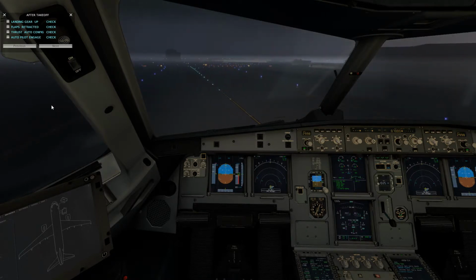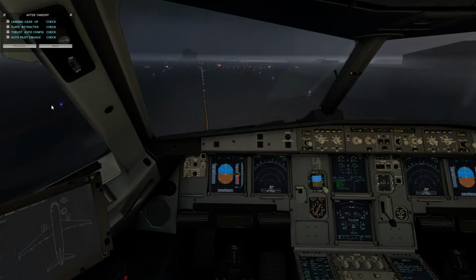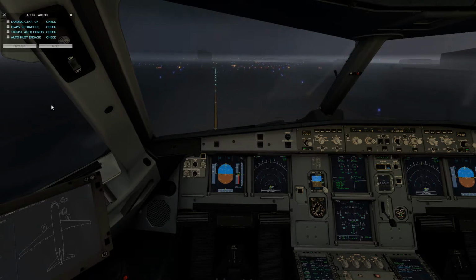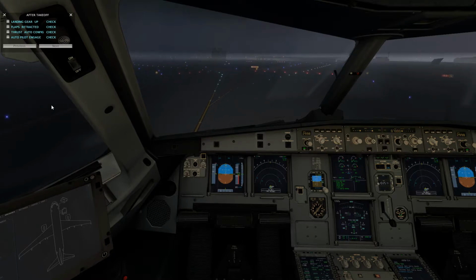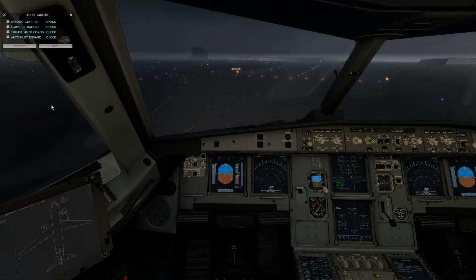Now the throttle on the Airbus A320 is a little different than some of the other aircraft. It uses the positioning on the throttle to actually engage things like auto thrust, and if it's not set in the exact position, your auto thrust won't work, and you'll find your plane doing crazy things, and it won't hold to the VNAV either.